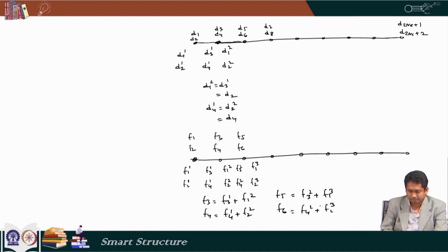So, now combining all the equations. Now we have the finite element equation, the 4 by 4 system from the first element and the 4 by 4 system from the second element. In the equation for the first element we have terms like D31, D41; instead of calling them D31, D41 we can call them by their global number D3, D4. Similarly, in the second finite element equation set we have D12, D22 and instead of calling them D12, D22 we can call them D3 and D4. And similarly, we have force and we can add up the forces and finally, after adding up.